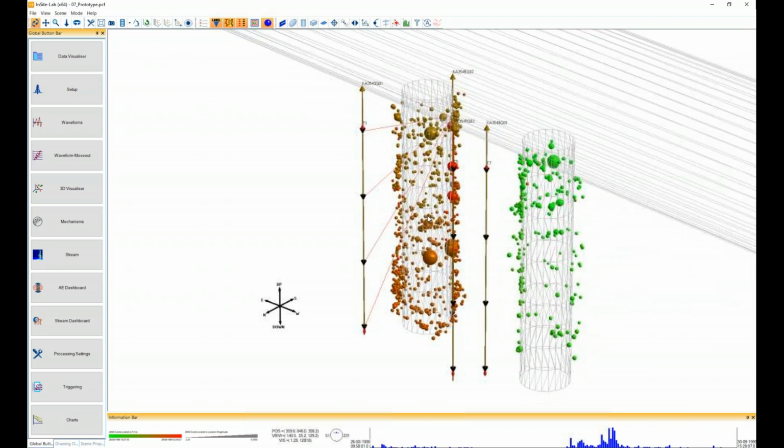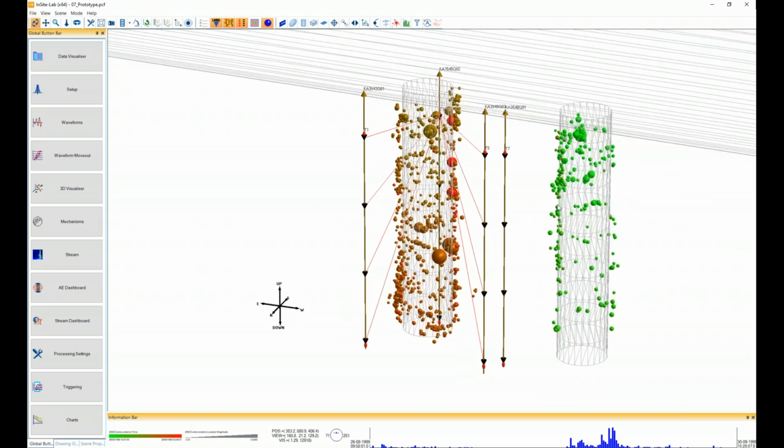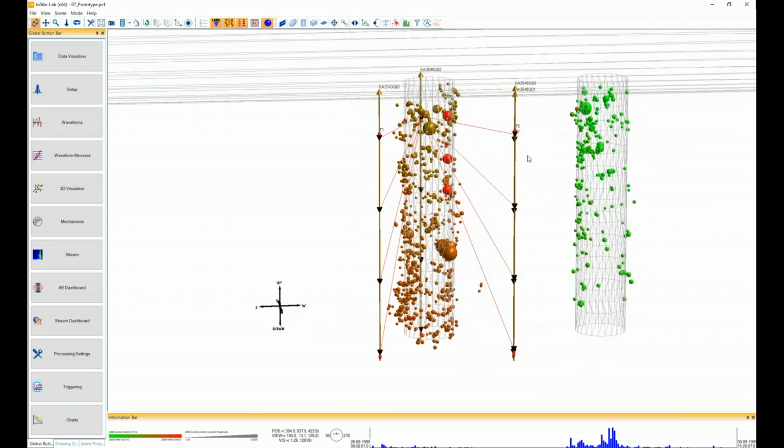In this case, it's a couple of very shallow boreholes, 7 meters deep, built to mimic the repository boreholes for nuclear waste canisters. They are subject to some loading. We want to see how the damage zone behaves when subject to these thermal stresses, and we can see that there are events induced around them.